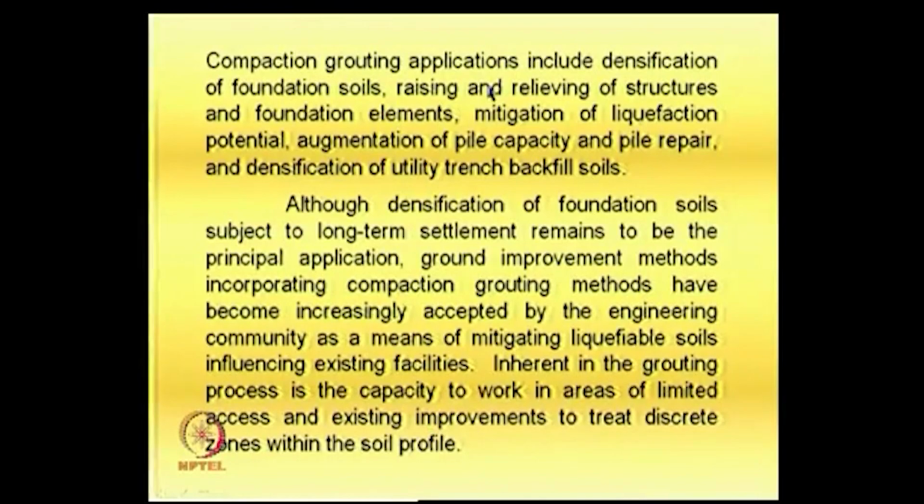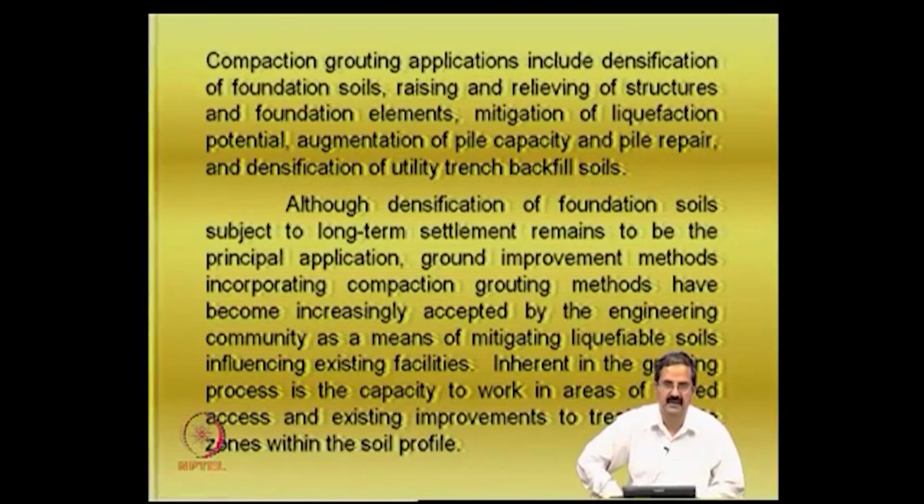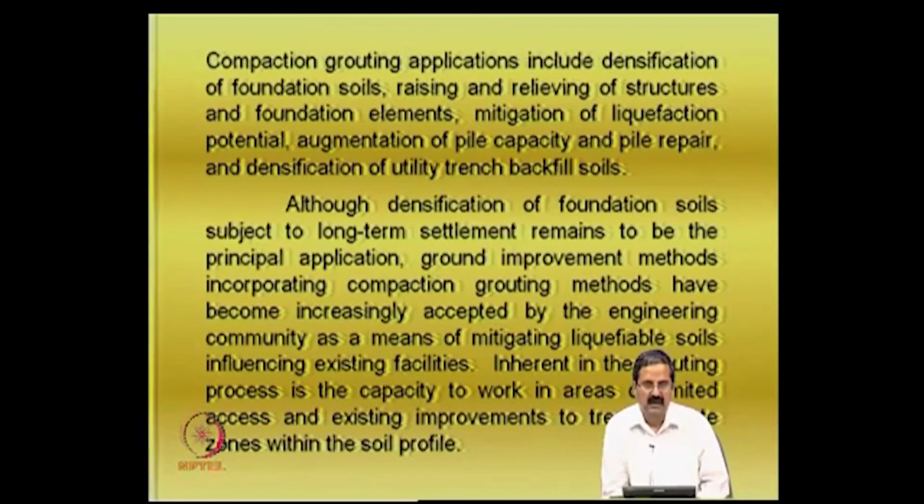So, the compaction grouting applications include densification of foundation soils, raising and relieving of structures and foundation elements, mitigation of liquefaction potential, augmentation of pile capacity and pile repair, and densification of utility trenches, backfills. So, for example, you know that the piles that you have designed may not have adequate strength or capacity, then how do you go about repairing it or improve the capacity of the piles? This is a very good remedial measure, a restoration measure, when there are no other ways of doing it.